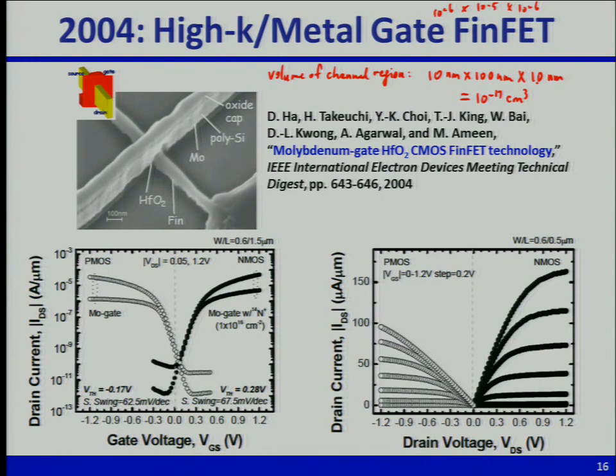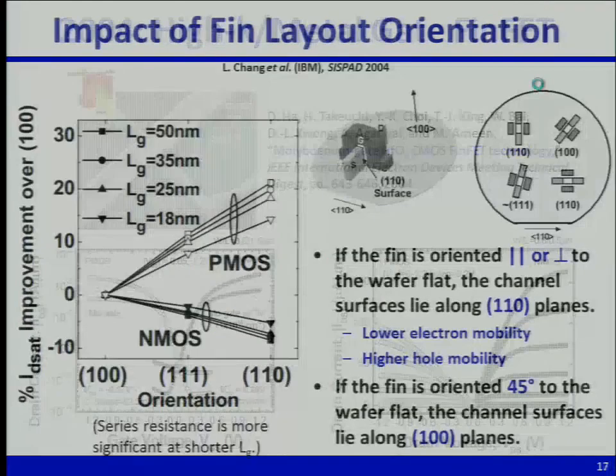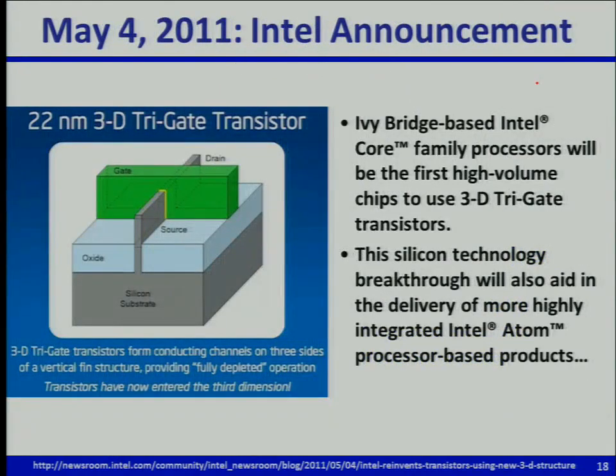So VT variation actually gets much worse in a FinFET if you try to dope it to control the threshold voltage. Now, if you dope it really, really heavily, like in the source and drain regions, simply to get conduction, it's OK. But fundamentally for the FinFET, it is not a good idea to tune the threshold voltage by doping, because that will result in too much variability. Sigma VT, the standard deviation of variation, can be pretty high once you scale the FinFET down. So that's not ideal.